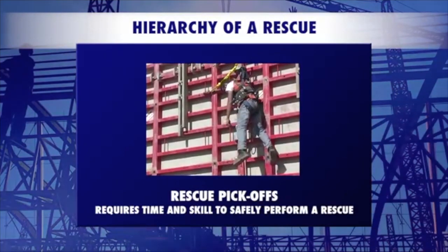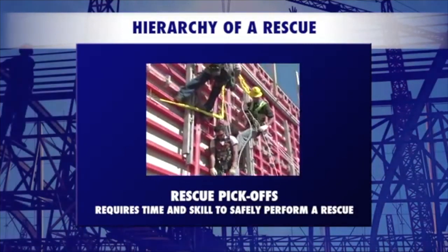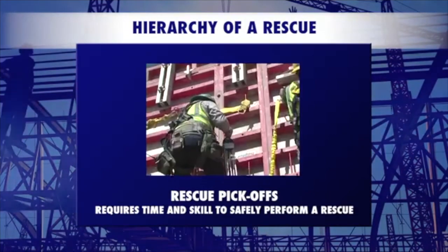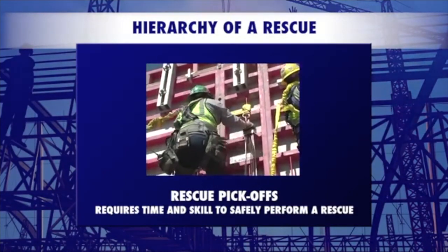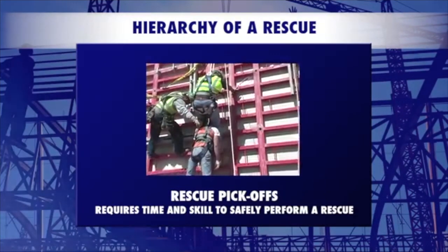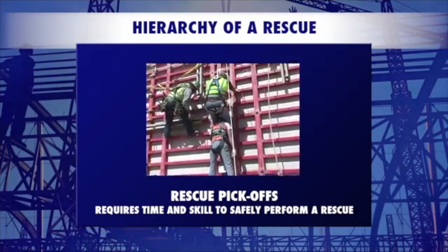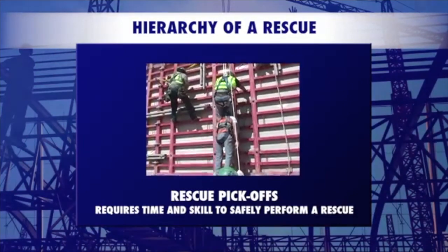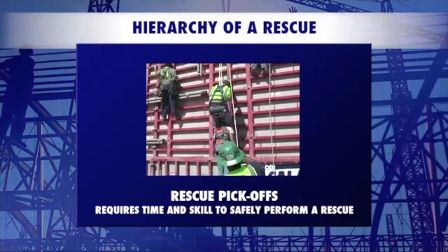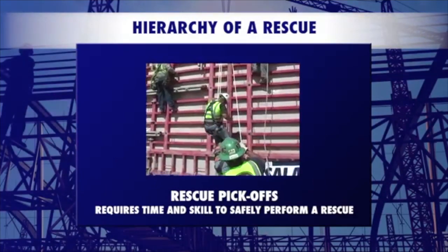Rescue pickoff. A rescue pickoff is a last resort because it requires the most time to accomplish and the most skill to safely perform a rescue. However, rescue as the last component of a fall protection plan is a good problem to have. A rescue situation means the worker was wearing his harness and attached to an anchor, thus making the fall protection plan a success.